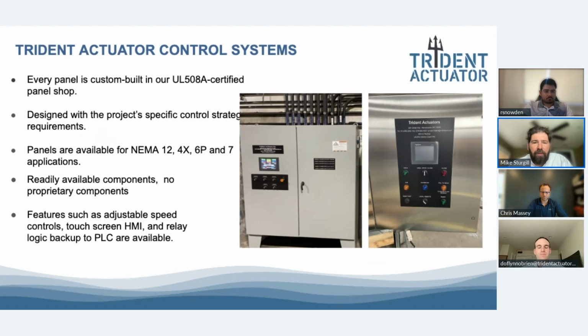You can get whatever you need to repair something in the control panel. For the standard control panels, the one more on the right, there's one panel for every actuator, with an HMI and redundant knobs for ease of use. You can work in local or remote. We have SCADA integration and relays for the end users. The one on the left is actually from that large project we talked about in New York City, and there are four actuators inside this cabinet. They just chose that because of space and configuration. But same thing, an HMI panel showing the different actuators and redundant knobs.